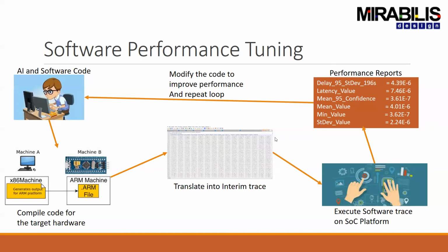It's a CSV format file where we are going to input this trace into the Visual Sim environment. Once we feed that into the Visual Sim environment, we will run these traces line by line through the entire system. Once we run it through, the Visual Sim Architect will generate the performance reports. This will include the latency for running the software, then the hit ratios, then the prefetch, then the write backs, then how many of them were evicted. So the write hit ratio, read hit ratio, all of that we will know from the Visual Sim Architect.